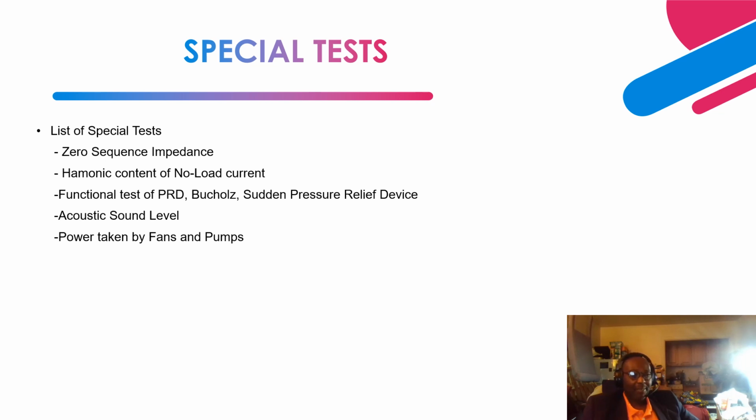There's a piping called downcoming piping that is sloped at an angle of about 7 to 8 degrees. In the middle of that is the Buchholz device. The Buchholz relay or device performs three functions. The first one is that it identifies when the transformer has a low oil level. Remember, the conservator tank is the one that replenishes the oil in the main tank. If the oil in the main tank leaks, the conservator tank replenishes that oil.